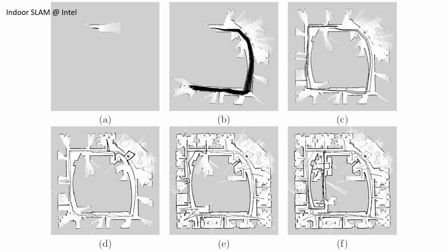Now consider that your robot is a mobile robot and it is moving inside a building. So it is an indoor scenario. Now, if it is moving indoors, oftentimes the environment needs to be mapped. And for that, there is one approach called simultaneous localization and mapping, also called SLAM. It would mean that not only is the robot mapping, it is also, in a simultaneous fashion, localizing itself vis-a-vis the other arrangement or the floor plan of the building.